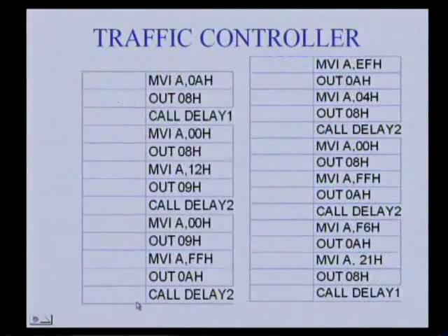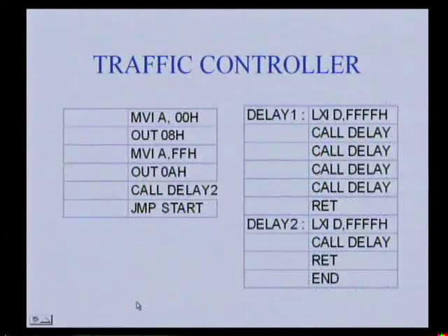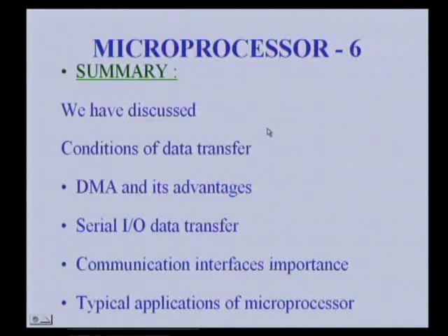The program listing is this, you can download this. The logic is we take the byte to be sent to the LEDs into the accumulator, and we simply output that to that port, that is all, and we wait for delays. These are the delay subroutines used. Okay. So this is the one application. Next, there are so many other applications you can check in your laboratory.